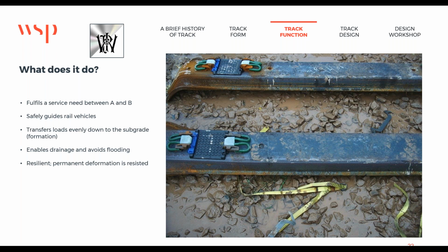Many track bed problems begin where track drainage is not operating effectively, or where changes in the position of the water table have created the need for additional drains. Ineffective track drainage can result in temporary speed restrictions or temporary closures of the line, increased maintenance costs, and poor drainage can even disrupt signalling equipment. Track circuits can fail if the formation is too wet.